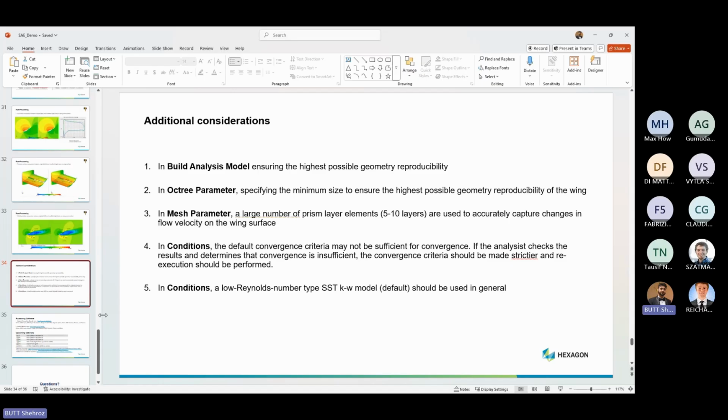It is always worth having a sanity check. By starting to look into your analysis model, you want to make sure it is accurate enough. It wasn't the case in here, but if you were to analyze an object which is much smaller than your domain, you will need to play with your faceting settings to capture the geometry accurately.